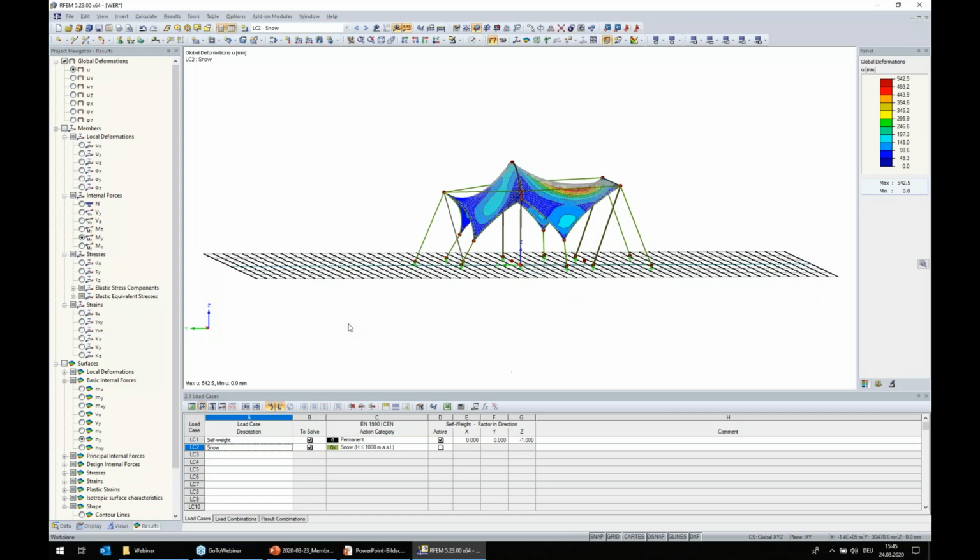And this was our challenge to develop a new program called RWIND Simulation. This RWIND Simulation is in fact a numerical wind tunnel where we can place any type of model and load it with any wind flow and get the reaction, let's say the surface pressure from it.